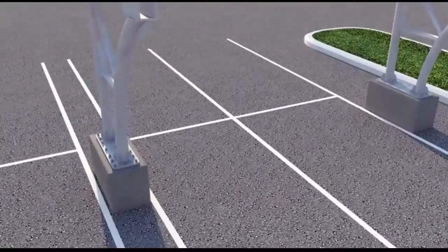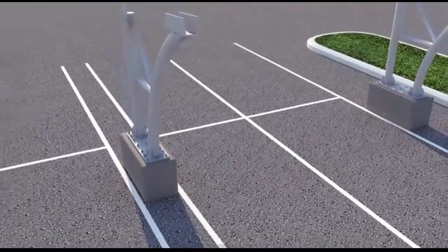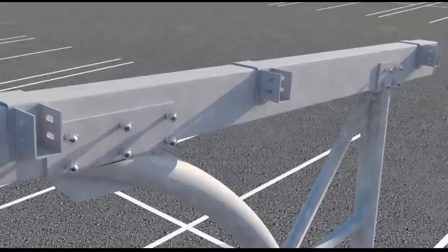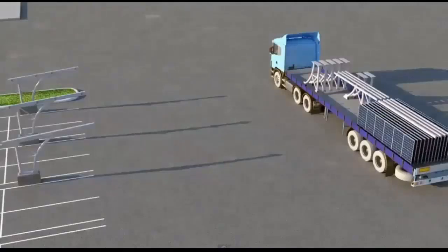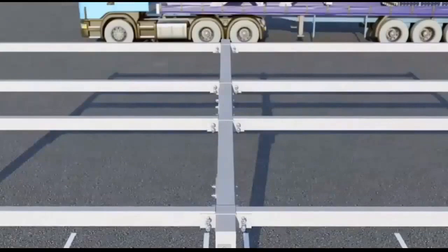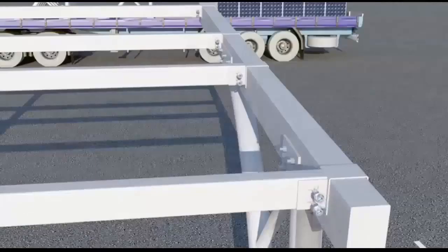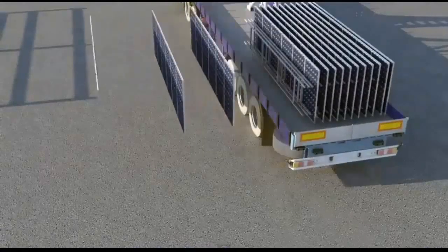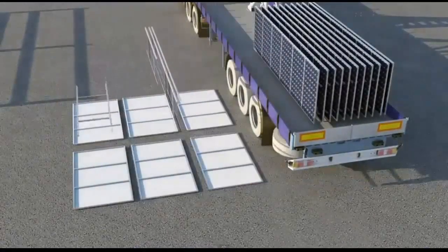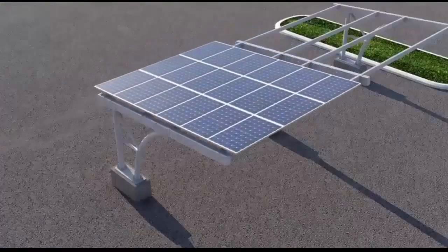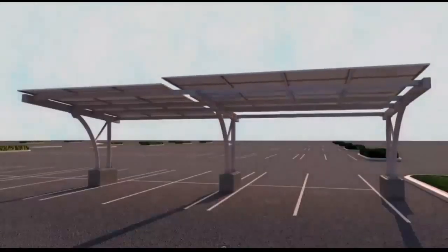From an installation perspective, pre-assembled kits can be delivered and mounted faster than virtually any roof structures and cables can be pre-wired on the structural elements of the frame, reducing the cost of on-site electrical work. When considered for lighting purposes, a base case credit could also be attributed to relevant projects. Finally, solar carports can easily be converted into electric car recharging stations and provide an additional source of income through sales of electricity to vehicle owners.